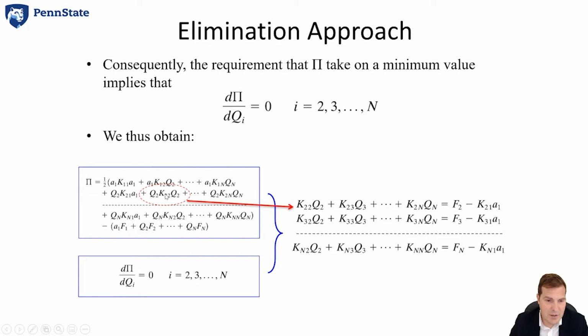And that process continues all the way down. It does help to expand this and work it out, but going through that process, you're left with something like this. So what it does is it allows you to move those values with applied displacements over to this side. That's one artifact that you get. The other artifact you're left with is basically all your unknown values, Q2, Q3, etc., all the way to Qn, which are still left on this side.